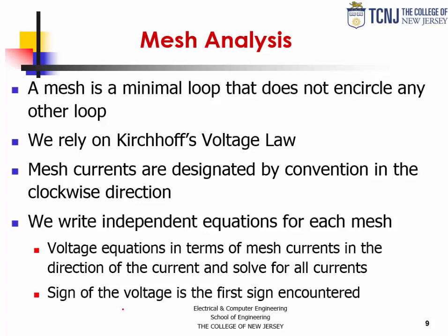And in this analysis technique, we're going to rely on Kirchhoff's voltage law to write equations for each of the meshes that are written in terms of the mesh currents. And we'll see how that works. That's going to yield independent equations, just as with the previous technique, that we're going to be able to solve using the techniques of linear systems or matrices. And once we know those mesh currents, we're going to be able to use Ohm's law to derive all the quantities that we would be interested in the circuit.